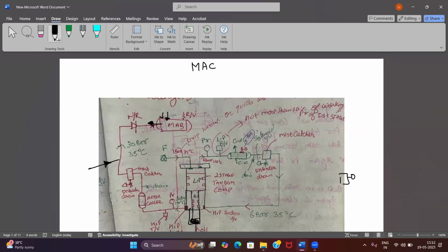Sir, but there is a non-return valve, right? Yes, I agree, non-return valve, that's why I didn't tell you exactly the main air bottle pressure, but approximately. Use the word approximately for your air bottle pressure. You have a non-return valve, your air cannot flow back. But after compression inside your cylinder, it comes out into this line, and that is when it is going to expand a little bit, and it will show lesser pressure as compared to what is generated inside your unit.